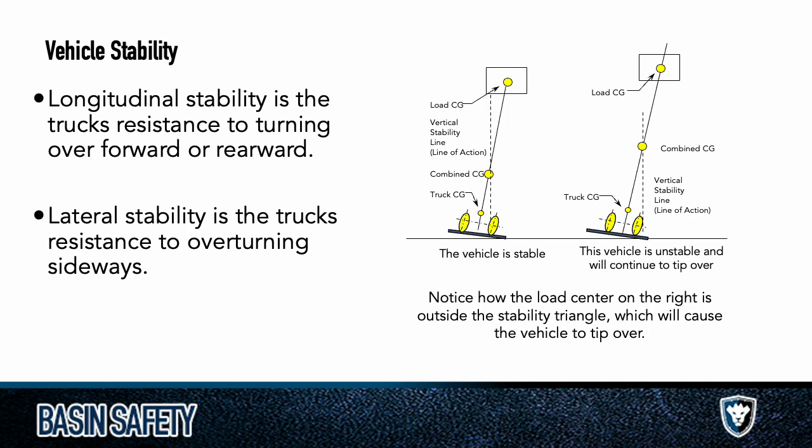So as you have a load on the equipment and you lift it up, the center of gravity will change. It will rise with your load. And so when you're traveling, especially, because the center of gravity has changed from the base of that equipment, which is where it is when the load or the forks are completely down at the ground, as you lift that load up and start to move, or even as you're holding the load, the center of gravity will change. It will change with the position of that load.